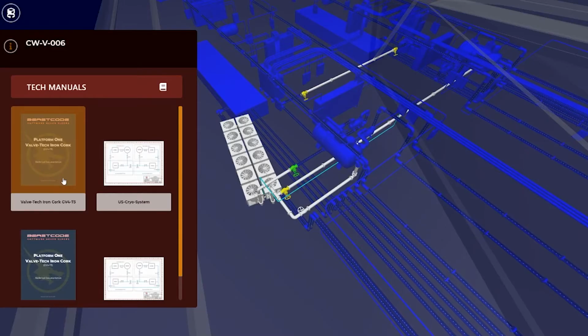And it goes a step further than just saying, hey, we found the name of this component and we're linking it up to the 3D model. Once we find more information about it, we might have a valve that's named X, but once we identify that it's a ball valve, we can then link it to the tech manual for ball valves, and then all the knowledge contained within that manual, we can start to pull out as well. So we might now have different symptoms and how do we react to it, or different parts lists that are used for supply and ordering. So super powerful that we're not having a subject matter expert or a data analyst tagging these things together, all done with automation.